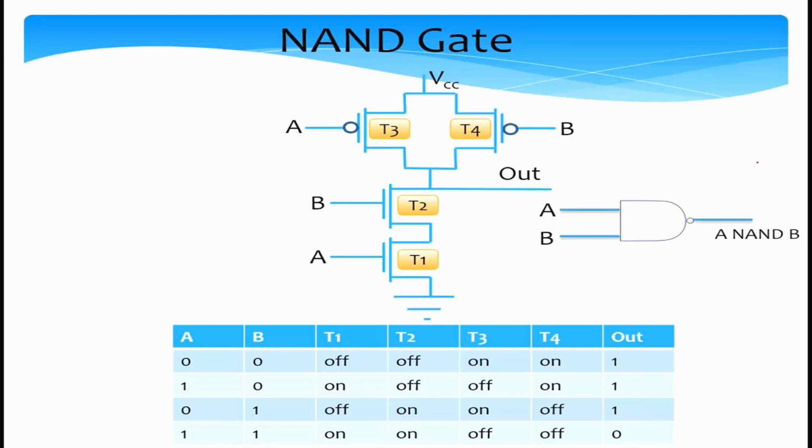So let us now take a look at the NAND gate. The NAND gate is essentially conceptually the same thing as NOR, where we compute A and B and we take a logical complement of this. So this becomes A NAND B. Here we have a similar looking design, very different though if we start taking a look at the details.